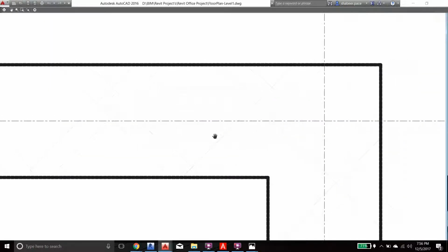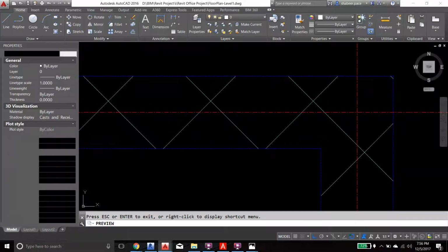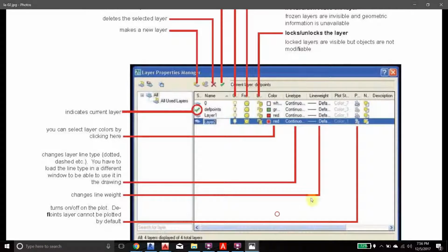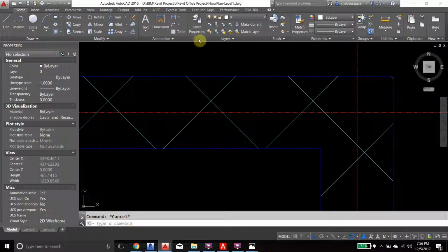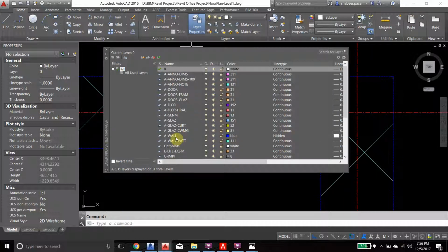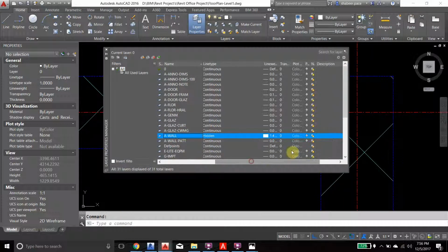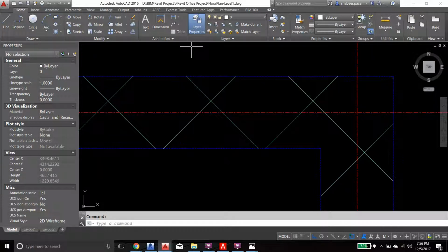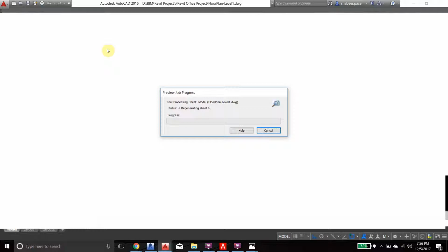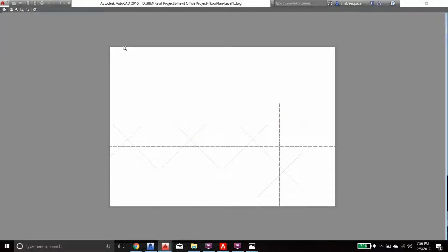You see. So sometimes you want to show your line dark, but in the drawing you want to keep it very simple. So then you can play with the settings here. There is a line weight, and you face this problem before printing. If you come to the drawing and layer and the wall, and you set non-printable and close it, and if you see the preview, can you see the wall?